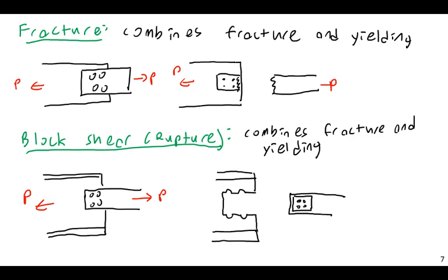I can make either piece fail in any mode I like if I select my dimensions and my material properties just right. There's nothing saying I have to use the same type of steel for both my W section and my plate. Often they're not. Often there is a table that I'll mention later in the steel manual that shows what types of steel are used for different types of shapes. Your plate may be made of A36. That's not uncommon at all.